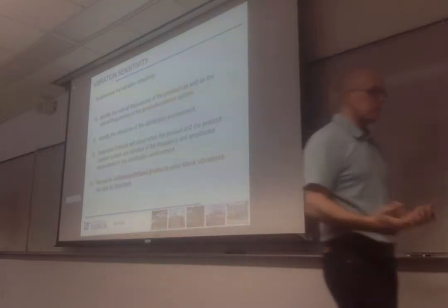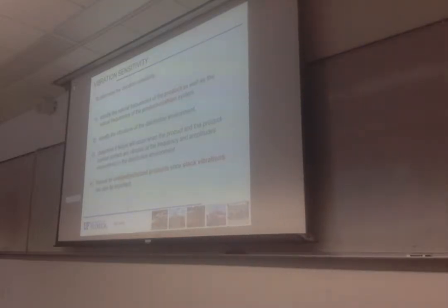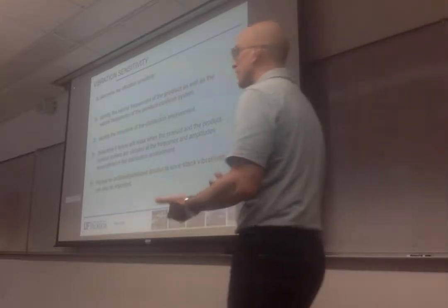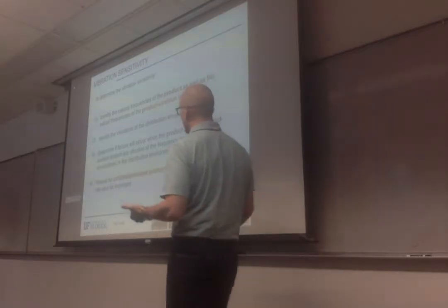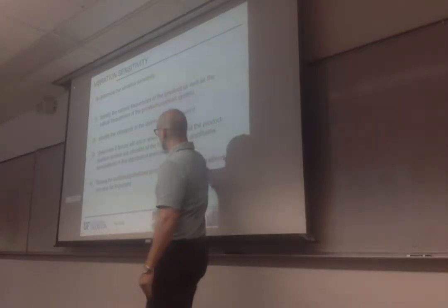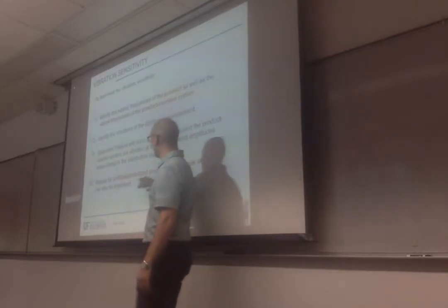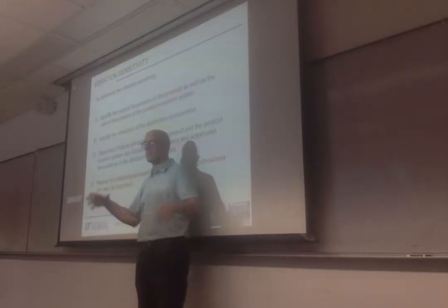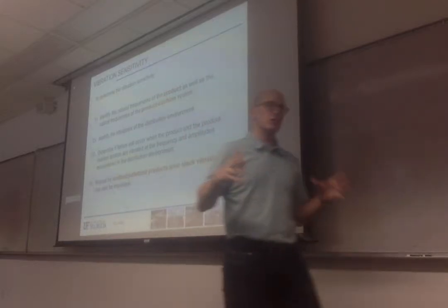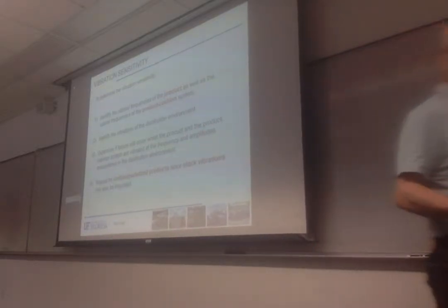So you may have some kind of resonance happening. But if the product doesn't get damaged by this, that's good. It's tough enough, it's going to take it, so you don't have to take additional steps to protect against it if you don't get the damage. And you also need to repeat this and look at unitized or palletized product. Unitized, palletized means the same thing: when you regroup many of these products together and you ship them together.